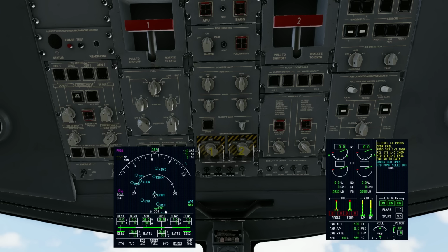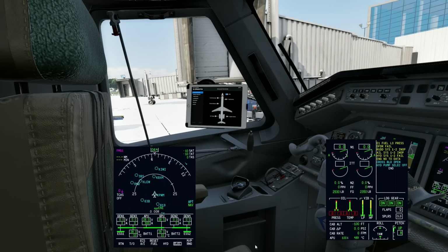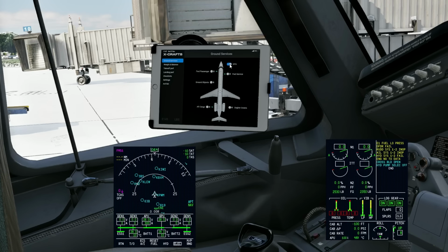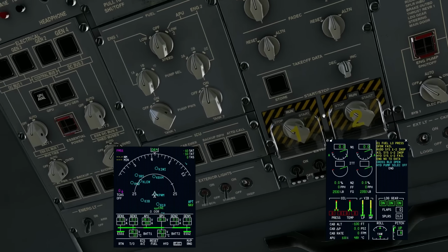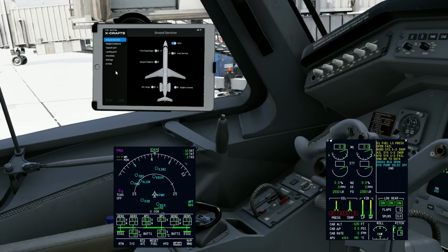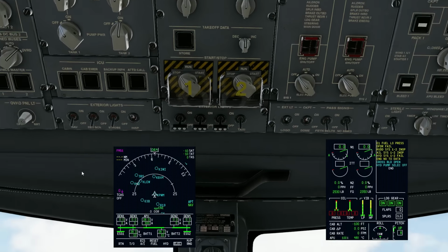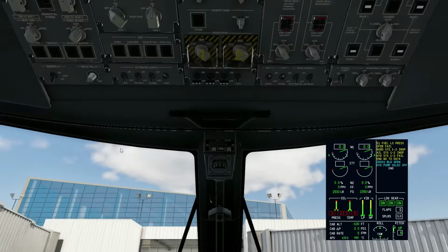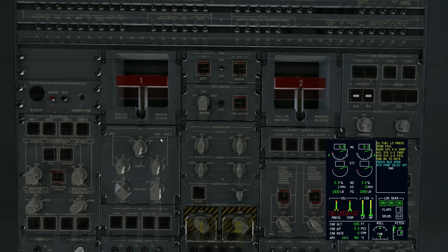In this case, we're good. We have a nice warmed airplane and things are running well, so we're only drawing 300 amps. Everything's great. APU showing 28 volts, which is its rated voltage. So that's good. We can go ahead. You can see that it's charged our batteries as well. And we can go ahead and deselect now, because remember, GPU is not being asked for, so be careful. We're not asking for it anymore. We can go ahead and deselect our GPU. And the GPU indication goes away. And we're now sitting here on the APU.